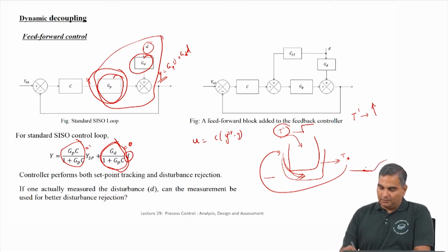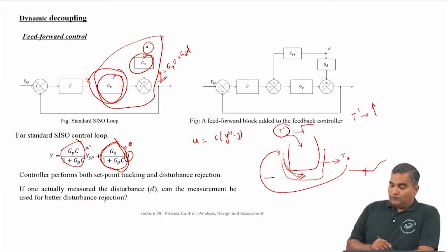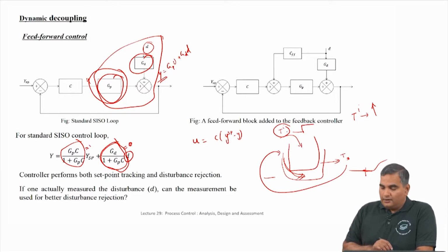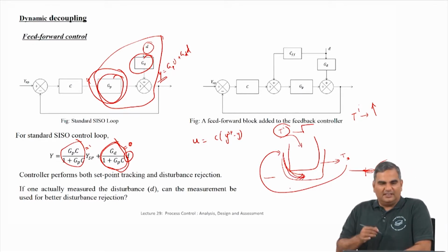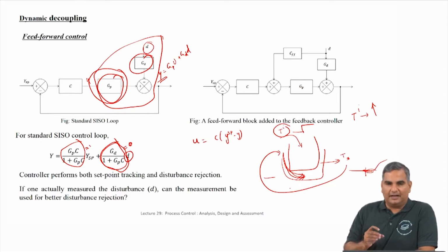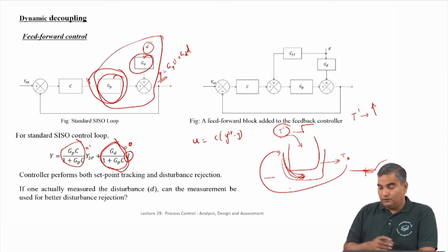Okay. So, this is the point at which actually Ti changed. I did not measure it, so I do not know that it happened. So, from a control viewpoint, what is going to happen is I have to basically wait for this time and wait for it to increase significantly before a significant control action is taken. So, in that sense, the controller is going to be kind of sluggish, because it has to wait before the effect of a disturbance is actually manifested in the control variable. So, this is a case where I never measured Ti.